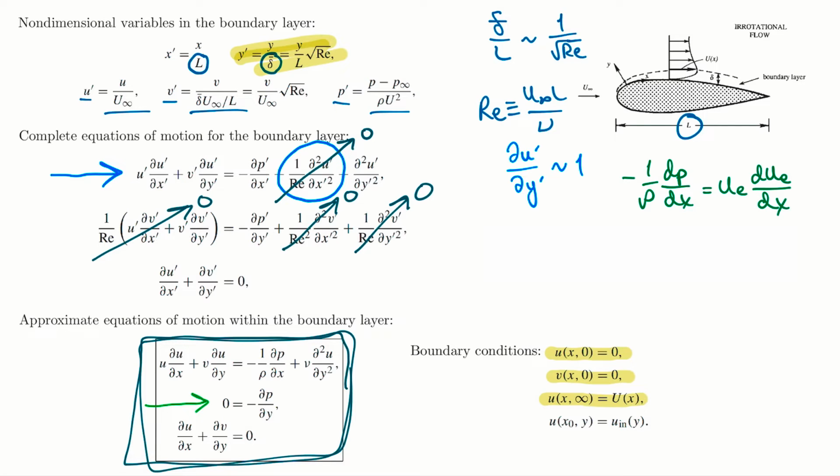And that's because we have these terms here, this one and this one, that will end up giving the boundary layer equations a parabolic character. So x is sort of playing the role of a time-like variable, which is similar to that suddenly accelerated plate that we solved back in section 4, where it was ∂u/∂t equals nu times the second derivative ∂²u/∂y². These problems are governed by parabolic equations. So the field at a certain time, or the field at a certain x in the problem here, depends only on its past history. So boundary layers therefore transfer their effects only in the downstream direction.